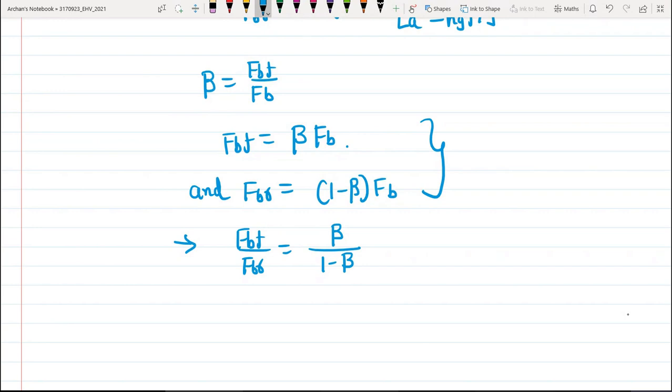It should be pointed out, however, that front wheel lockup does not cause directional instability. Whenever lateral movement of the front wheel occurs, a self-correcting moment due to the inertial force of the vehicle about the yaw center of the rear axle develops, and it tends to bring the vehicle back to a straight line path. So the loss of steering control may be detected more readily by the driver, and control may be regained by the release or partial release of the brakes.